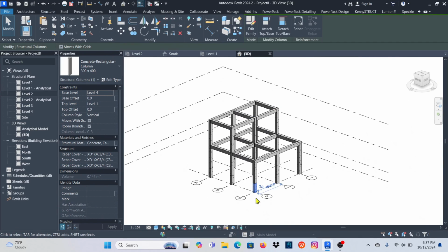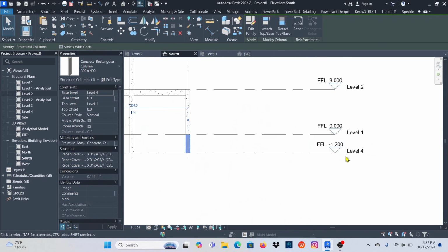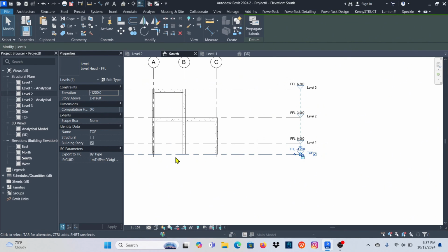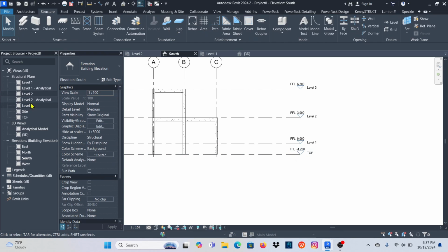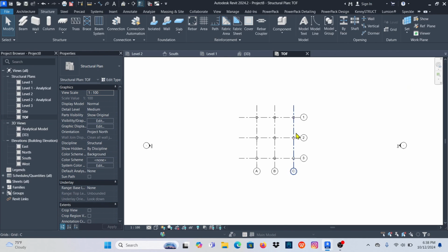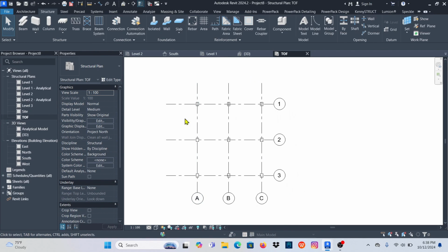The bases, it's simple. I just need to go to that level. If I go south, at south, this is level 4, but I can even change this one to maybe T or F. If you want, you can change this from here. Click outside and click on yes. Now let's create our bases right here. So if I change from there, it also changes from here. All right, double click. So now those bases, again, it's very, very simple.